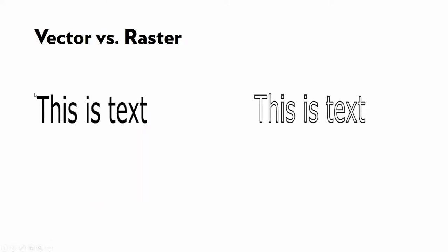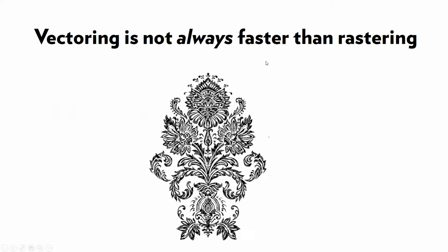And here, if we were to raster it, this would be how it would appear on the plywood or on the wood. And if we were to vector it, those lines would occur like so. So that's a real brief difference between a vector and a raster. Same thing applies to text. If you have text and the text is fully solid and you're rastering across it, then the laser would have to go across every line of that bitmap or JPEG or what have you. As opposed to if you made a vector outline of the text, then the laser only traces the outline of the characters of the text. So again, this is how it might appear as it's rastering versus vectoring.